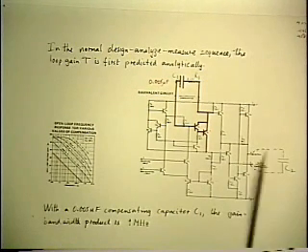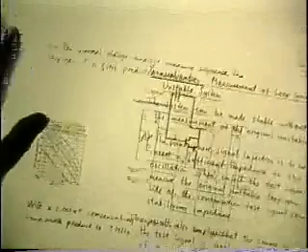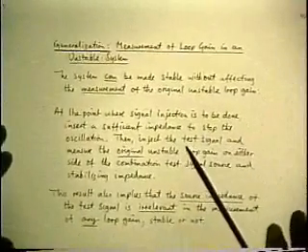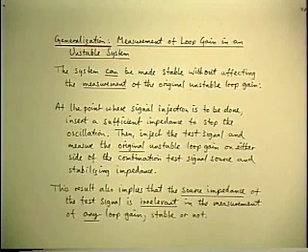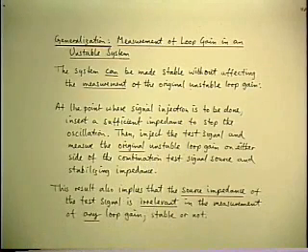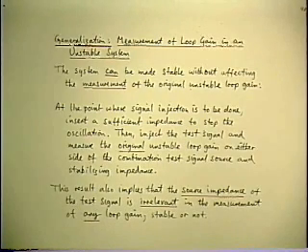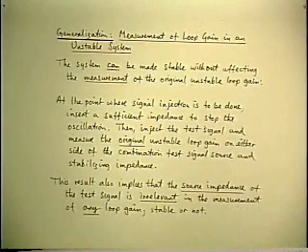So that's completed the process in order to illustrate this design, analyze, iteration stuff again, and that's the last point. You can, in fact, measure an unstable loop gain. And you do have to stabilize the system first, but you do it in a very particular way which allows you to measure the original loop gain before you stabilized it. So that's a useful technique. It gives you more power over the final results.